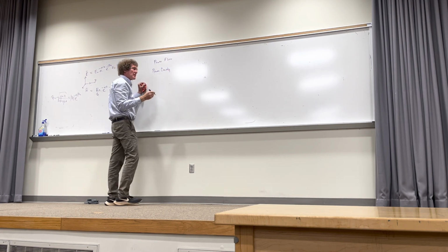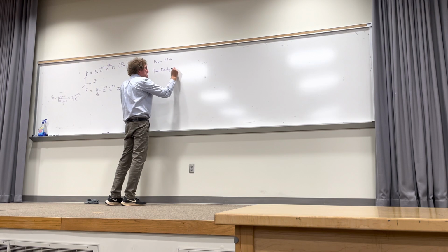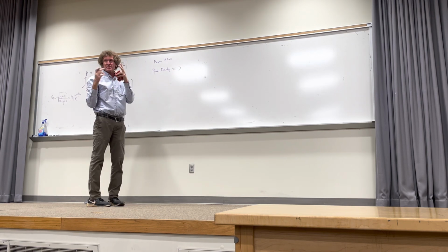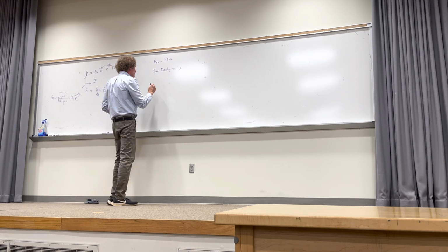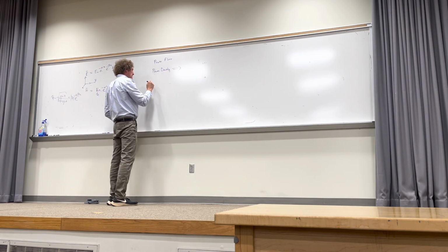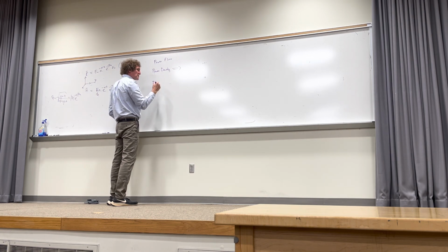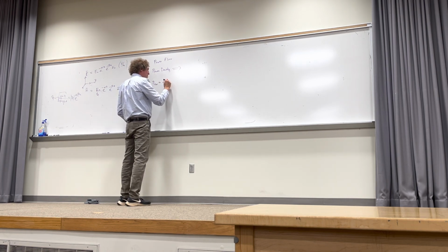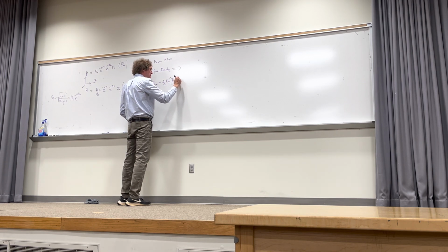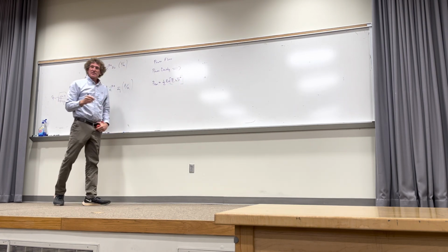Density of a wave. And when you think about power density, it's power, but it's not just power in watts, it's power per meter squared. So the formula, and this is in the phasor domain, the average power of an electromagnetic wave that's propagating would be equal to 1/2 the real part of E, the E field in the phasor domain, crossed into the H field, but the H field is conjugated. Y'all follow me on this, class?